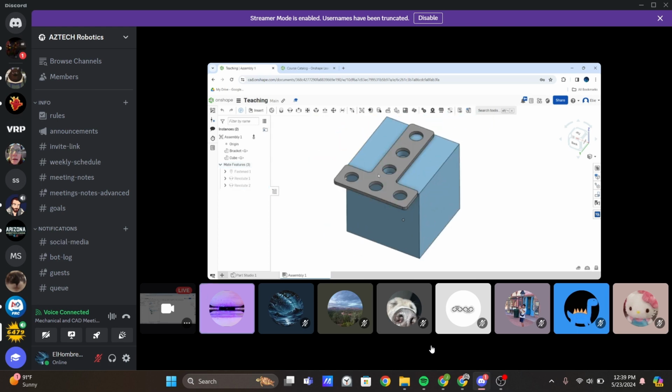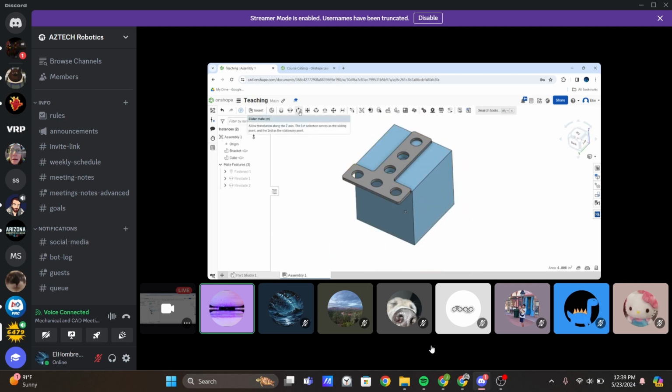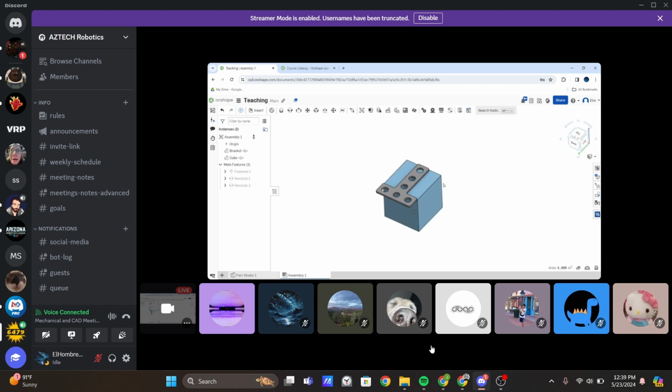So now this can't move because of both of these. The bracket is allowed to rotate around both of these points, but it can't technically do both. So now it's fixed in place. It's like adding 2 rivets. As for the other mates, I really don't use any others besides revolute, and then occasionally planar or cylindrical. I can demonstrate these better.